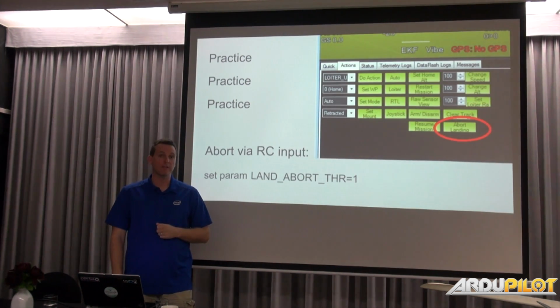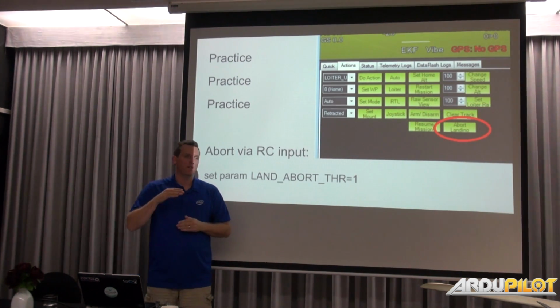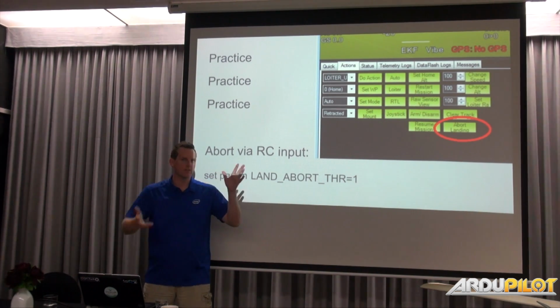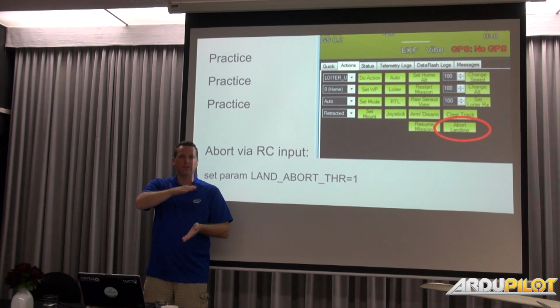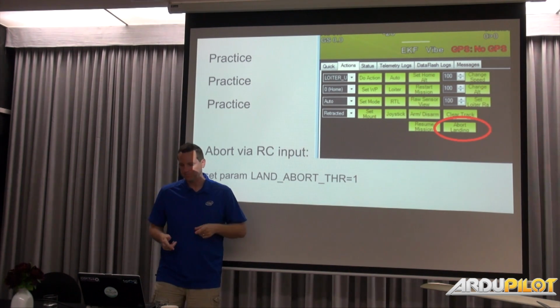And also there's the landing abort. So this is a good repeat pattern where you're coming in for a landing, and then you hit your pre-flare, which is 10 meters or so, and you will see how well you hit that point. And then you can just abort from there. You'll circle around, and then you can repeat that and tweak a parameter, and then try it again, and not actually land. Just repeat this process. It's much faster that way.